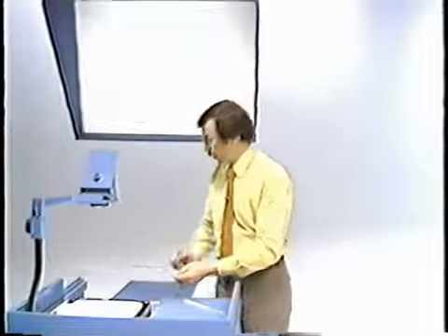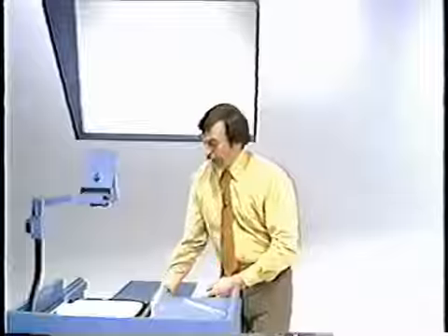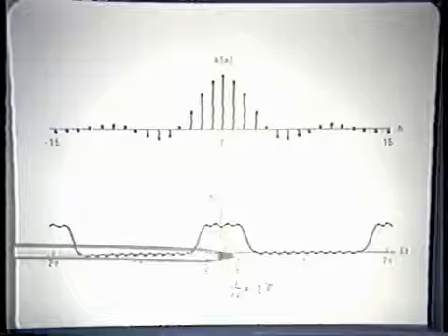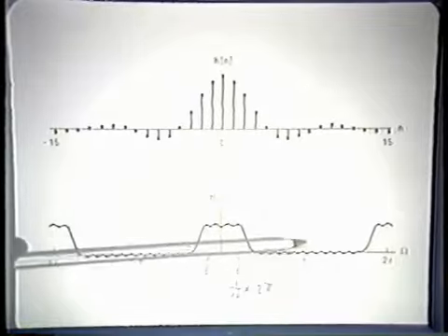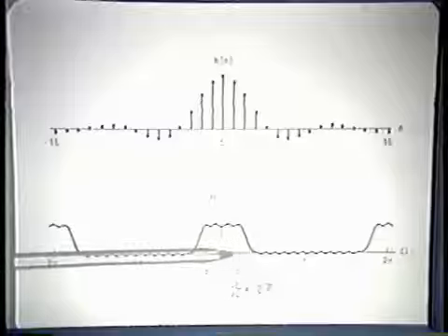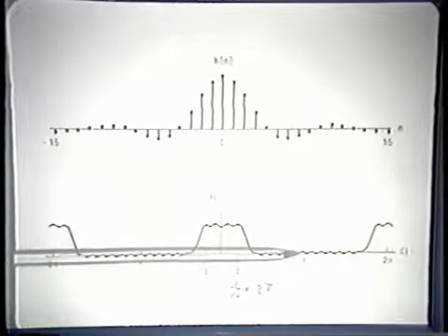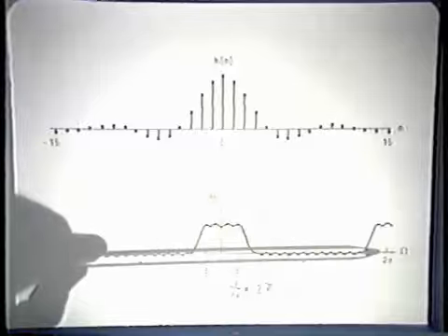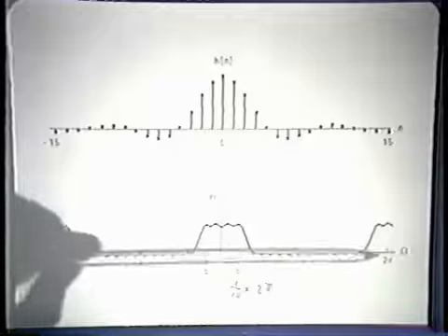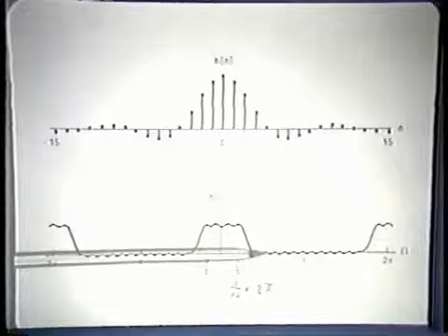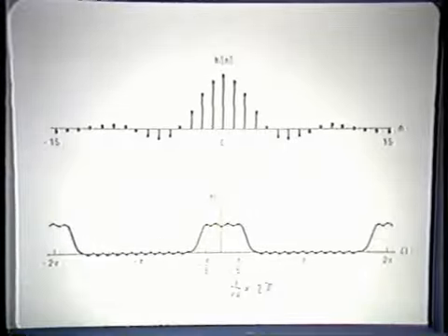Another way of thinking about that is that when we watch the frequency response of the system, as we look at the digital filter frequency response, what we're sweeping as we go from 0 up to 10 kilohertz in the input frequency is this portion of the frequency response. As we sweep from 10 kilohertz out to 20 kilohertz, what we'll see is this portion of the frequency response. In other words, we'll see it periodically replicated.